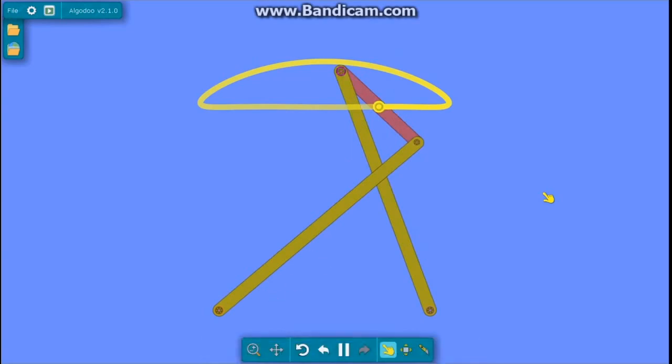This is called Chebyshev linkage. See, these straight line mechanisms are used mainly for components where motion in other directions is not preferred, so that it does not deviate from the straight line. For example, sometimes it is vertical or horizontal. Imagine a vertical one, for example a piston cylinder arrangement.